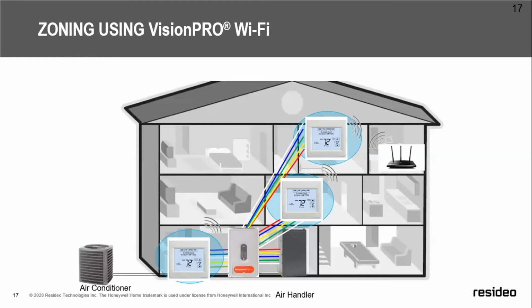Now, since we're using a Wi-Fi thermostat, we have got to have all the control wires, as well as the common and the hot wire, come into the sub base of the thermostat. Now we do have a wire saver device, so if you're one wire short, it has the ability to send zeros and ones down one of its wires.